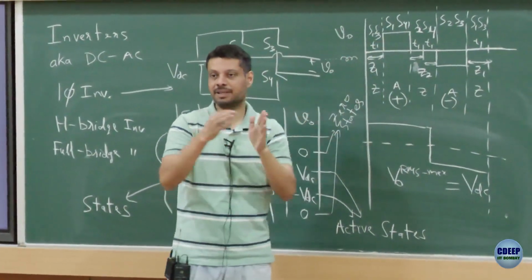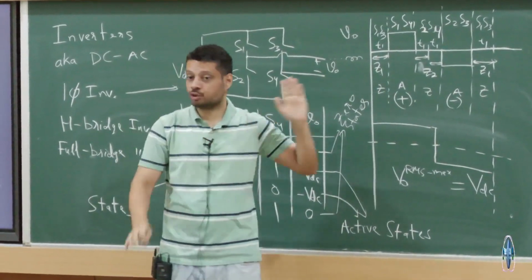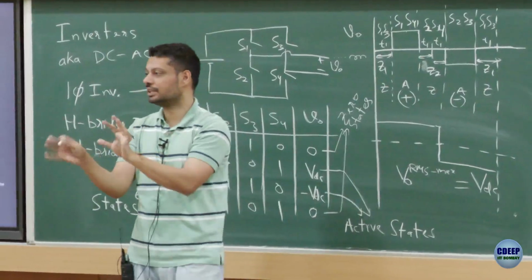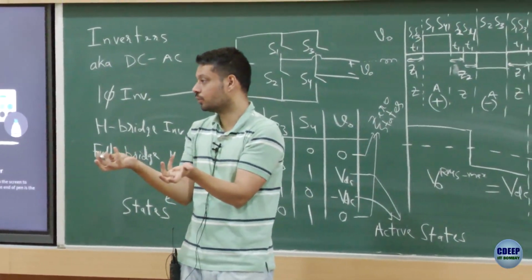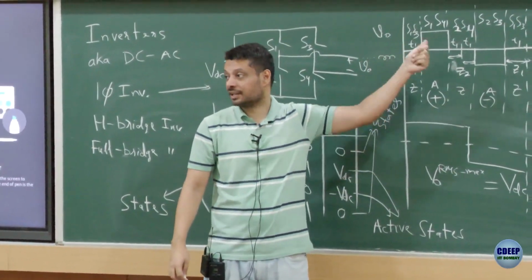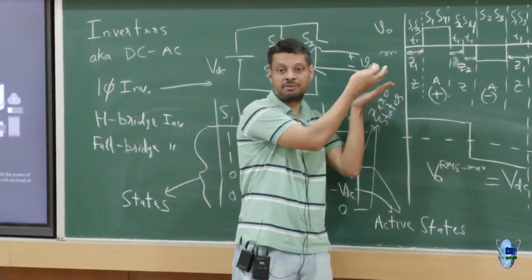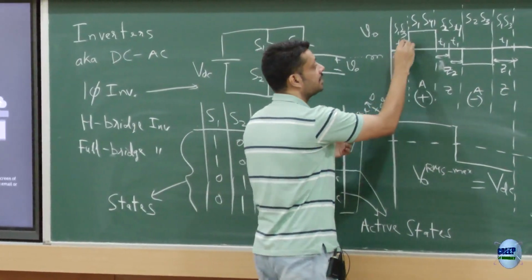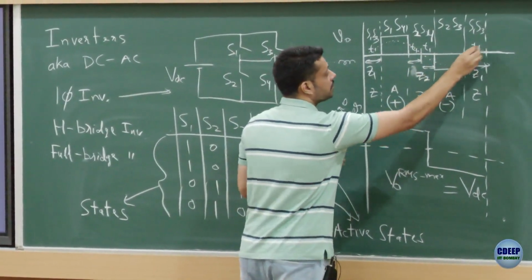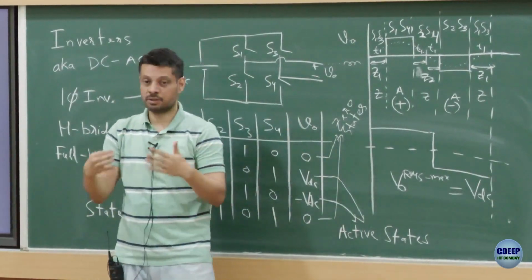This has multiple frequencies, right? If you just take the fan example again, actually you are only utilizing the fundamental component, because other harmonics are creating these oscillations, vibrations. They are of no use. So the main component being used is the fundamental sinusoidal, which is there. You cannot see it, but you can visualize it like this. There is a fundamental component which is there. So the fundamental RMS would matter more than the total RMS, and we will eventually see that.